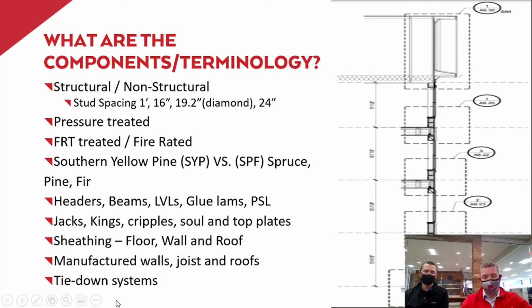It is a wall that is placed either on the corner of a building or within a building that is always sheathed with either drywall or plywood and has a very specific fastening pattern that must be adhered to. Shear walls are made for wind resistance for the building and earthquake tolerance. And you will always have a shear wall plan to go off of in your contract set.